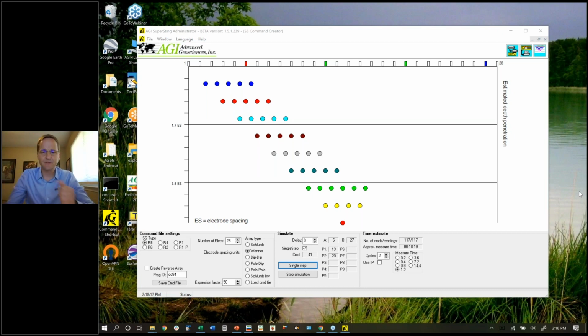So communication between the staff on the ground is critical, and just double checking everything. Imagine your C1 and C2 need to be at 50 feet, but one is left at the prior position for one reading. There'll be quite a bit of error in that reading. So in some cases you need walkie-talkies or talking on the phone, confirming and double checking everything.